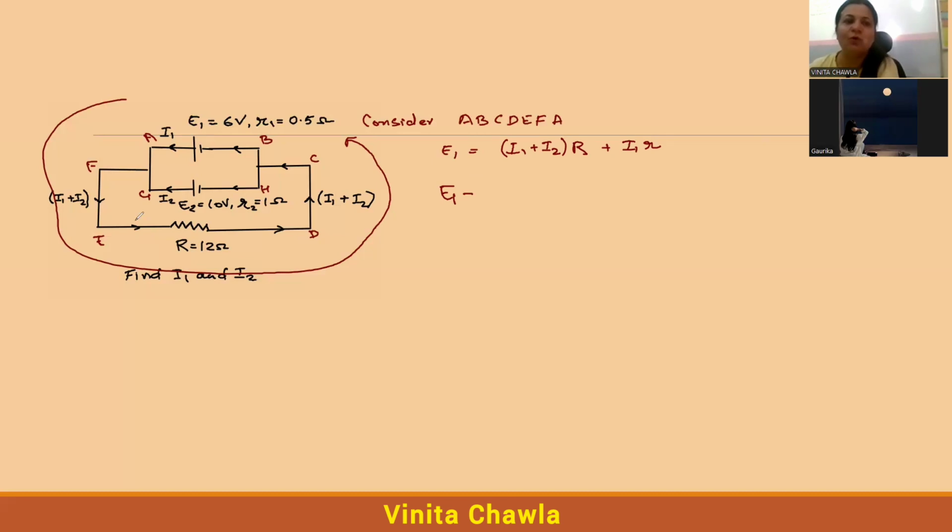Okay, then we go to this and direction of current, this is positive, this is negative, and current is moving from entering to the positive of resistor and leaving the negative of resistor. So we'll put a negative sign and then we'll write minus I1 plus I2R. Okay, and again it goes there, है ना, so we'll write minus I1R. So there is no harm in writing like this also.